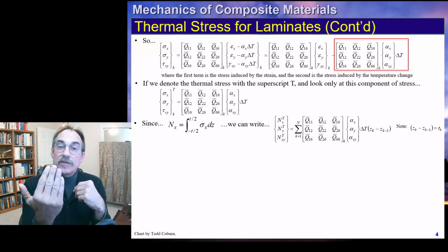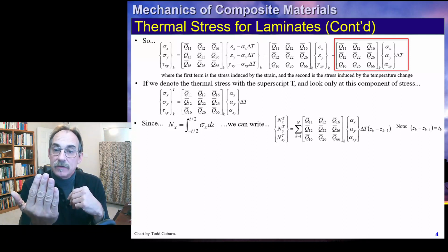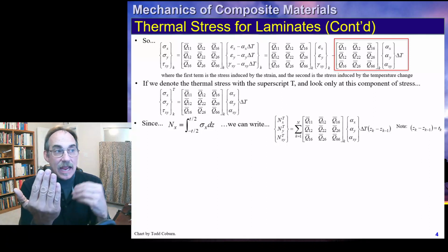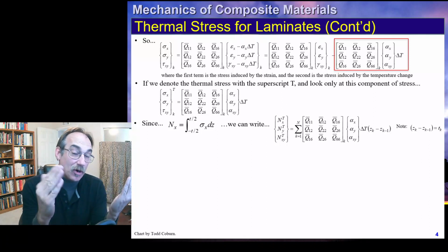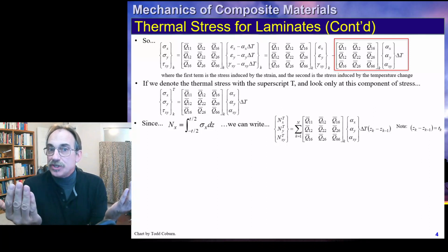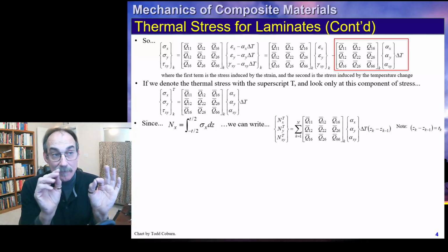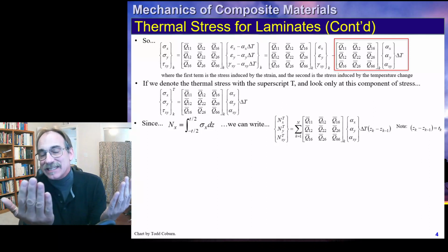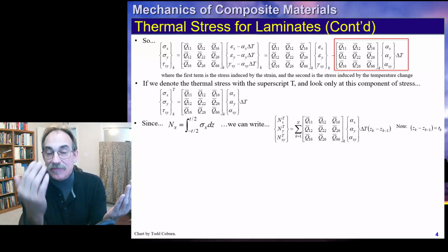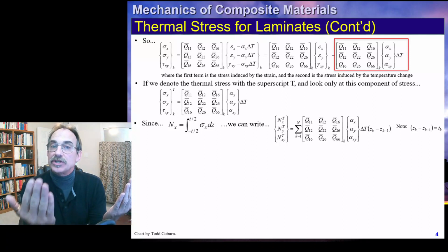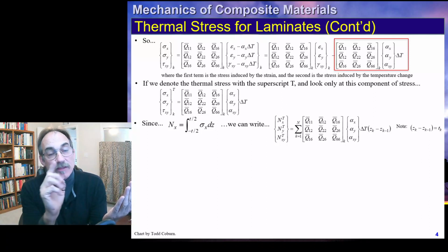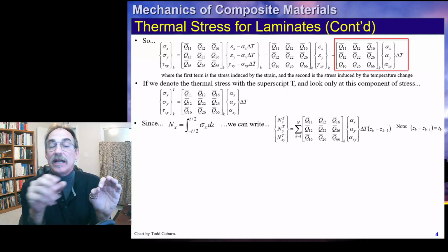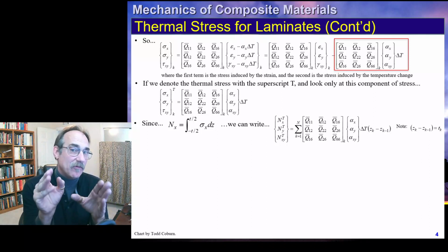And since we're dealing with a thermal strain, and we're turning that into a stress, but those thermal strains don't induce stress, what that means is these are the running loads that would cause the exact same amount of strain. And this is how we're going to account for that thermal strain, by figuring out the virtual or imaginary loading that would cause the exact same effect.